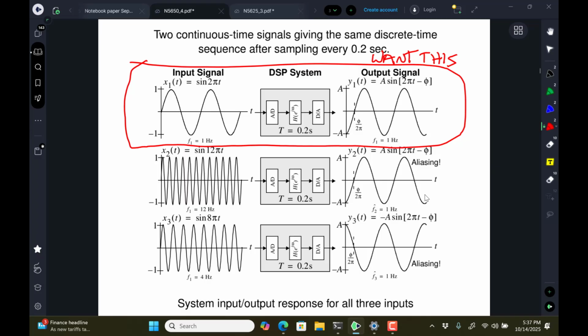You'd say, I like the programmability, but you've got to put down that A to D converter. You then have to have the computer that can run the algorithms for the filter. Then you have to have the D to A converter, the clock generator, and probably the anti-aliasing filter in front to protect it from letting signals above the folding frequency in, and then the reconstruction filter. So what do you have? You have some expense involved.